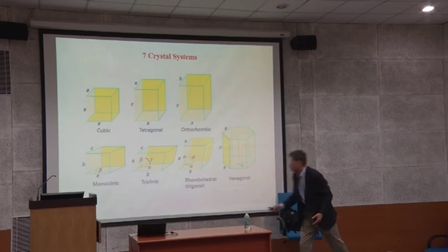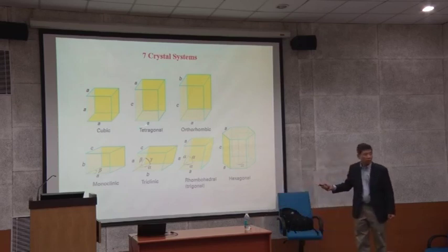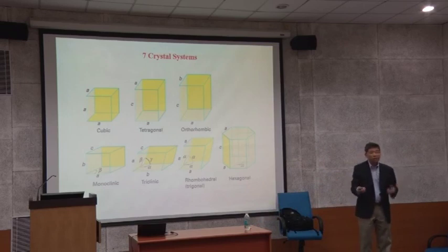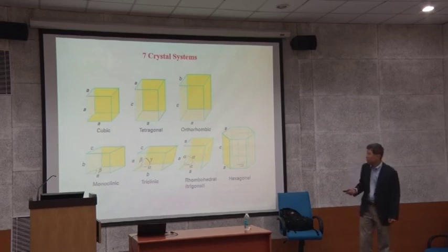So that's why in your tetragonal system you get another additional peak. And then with this one you get a splitting peak, and another one, so you have more peaks here. So you can actually determine the position of the peak and the number of peaks splitting, and you can tell what kind of X-ray diffraction work it is.